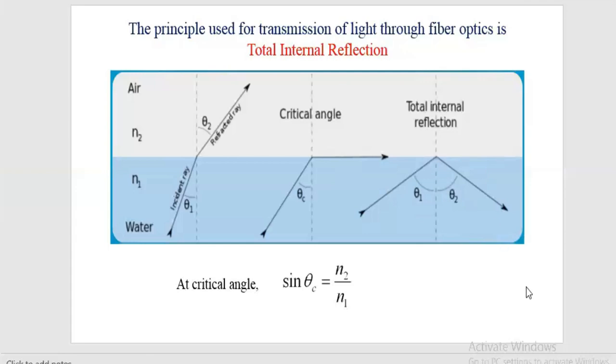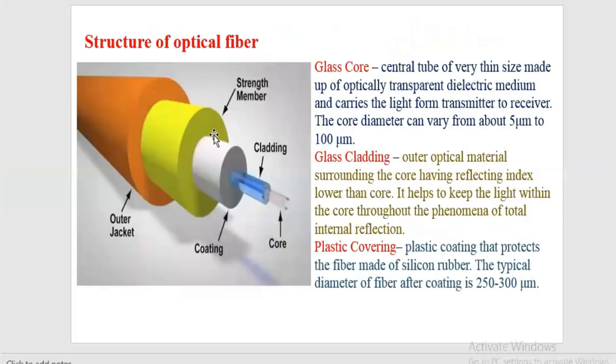So what does this optical fiber material consist of? These are long wires containing high refractive index material at the center, which is called the core. This core is surrounded by another optically active medium, the cladding, which has a lower refractive index than the core material, such that the total internal reflection condition is satisfied in the core.